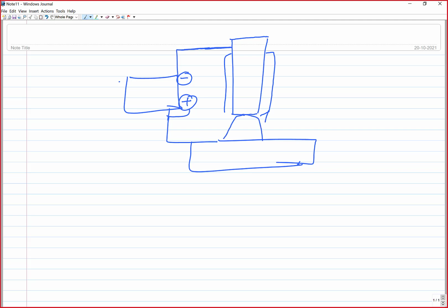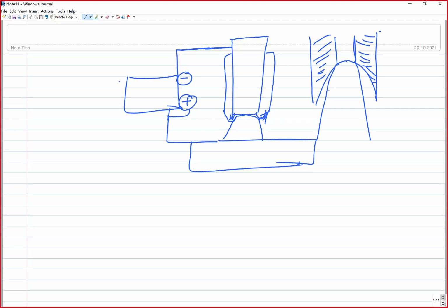You see, the coating burns at a lower rate as compared to the core wire. So always this is the coating and this is the core wire, and the coating projects beyond the core wire, with the arc coming out like this. This helps to constrict, or reduce the diameter of, the arc. That, in a very simple way, is how it helps to constrict the arc.